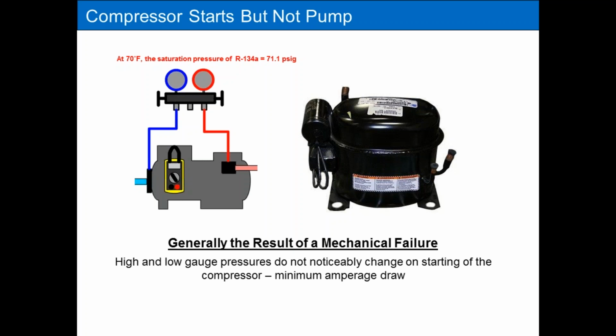If your pressures don't change, you start it up, measuring current, it's drawing current, compressor's running, but the pressures don't change or they change very little, you've got a bad pump and a leak. You've got two scenarios going on, and that is not uncommon. It is something that you may find, where a loss of refrigerant caused the compressor to fail, and you've got two things to deal with.